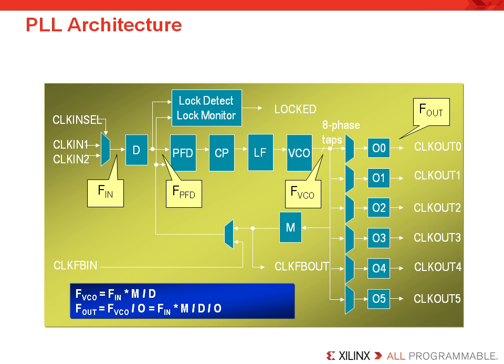Now, many different output frequencies can be made based on a programmable multiplier and divisor value that you can set for each MMCM. Each MMCM can have its own programmable values, that is a multiplier, M, a divisor, D, and an output divider, O. You can determine the range of values supported from the Device Clocking Resources User Guide.